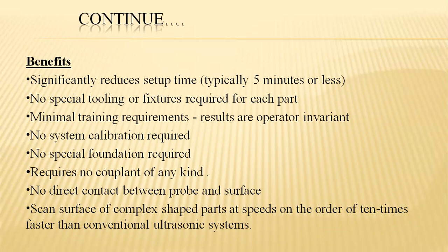But the operators need to be trained; a skilled worker is necessary to operate it. No calibration is required. No special foundation is required. No coupling of any kind is required. There is no direct contact of the probe with the surface of the part being examined.